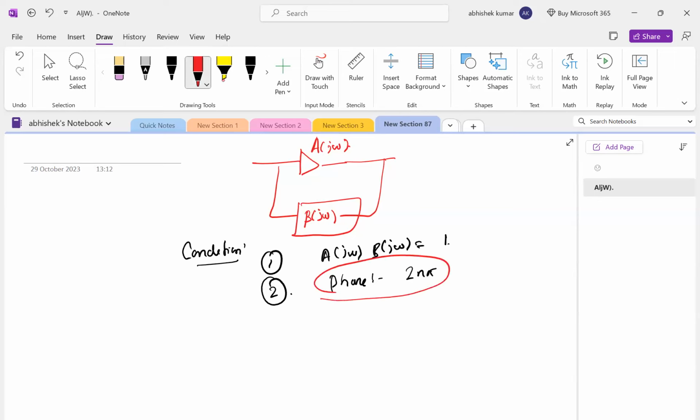After that we have the LC oscillator, the inductor capacitor oscillator. We have the quartz crystal oscillator. Every oscillator has its different advantages and disadvantages. LC oscillators have very poor stability. Quartz crystal resonators have good stability. So these we were dealing with in the last class.